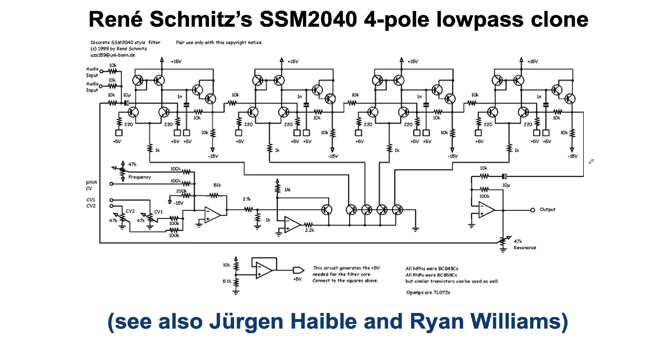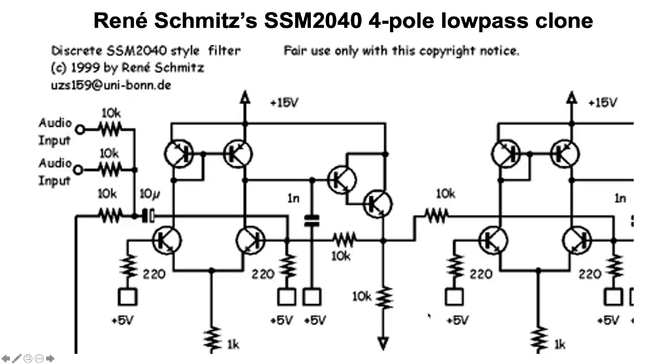And we have our feedback path here. And in this example, a potentiometer is controlling the amount of feedback. Here we have the individual stages. We have 4 filter stages. So now I would like to focus on just one of the stages. Don't let all of these plus 5 volts throw you. These are actually acting as a local ground, kind of the way guitar pedals that usually run off of a single-sided 9-volt supply will internally have 4.5 volts, acting as the 0 signal reference inside the pedal.